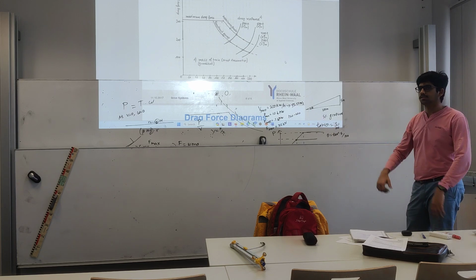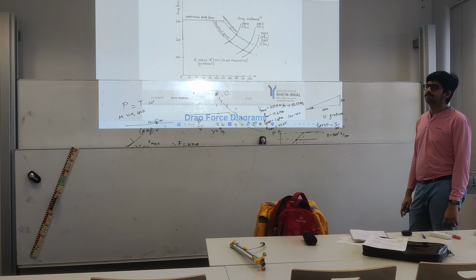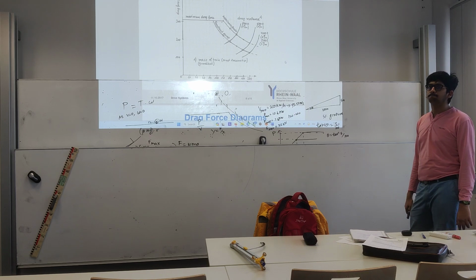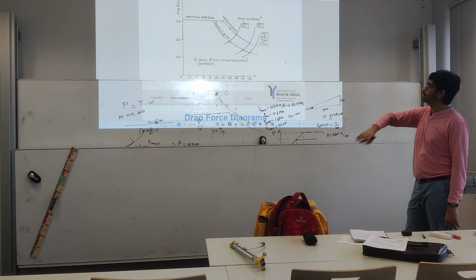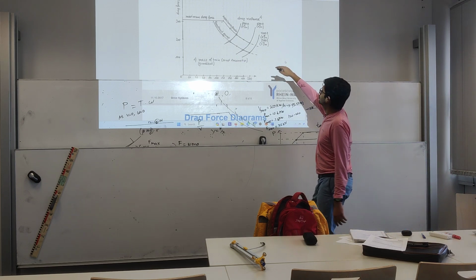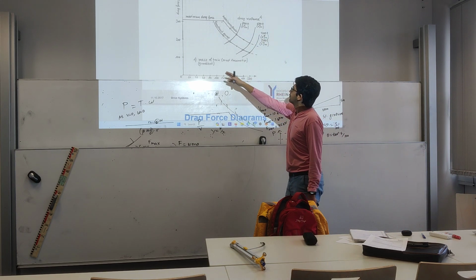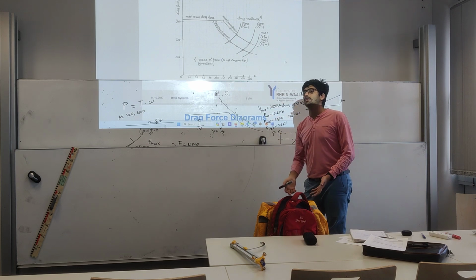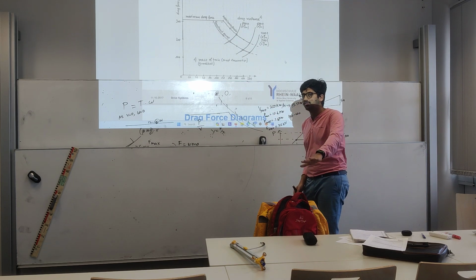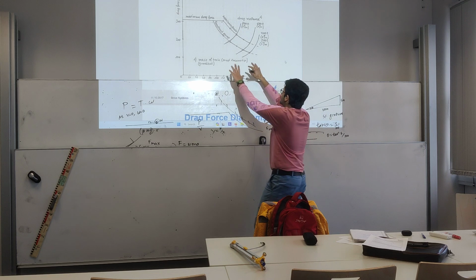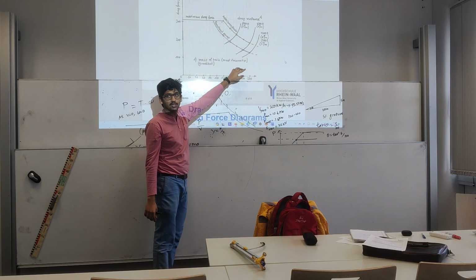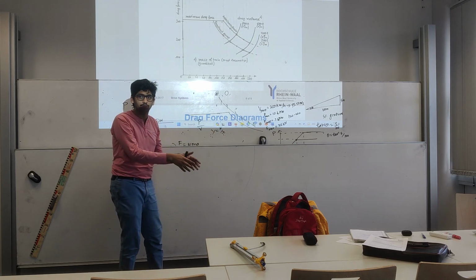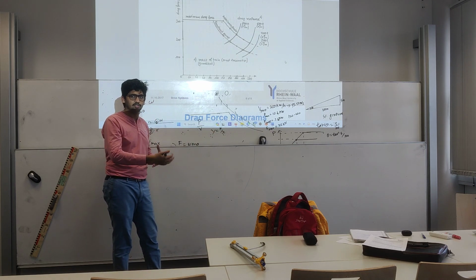No, drag resistance is not dependent on drag force. Drag resistance just tells you for this much load at different speeds how much drag force is needed. It doesn't care what is being given. See, in this graph we're drawing two things. So the maximum drag force and the maximum power lines, that's the input side, the locomotive. The output side is the carriages, which have the mass, right?